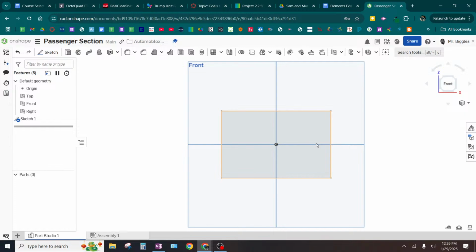And I'm going to measure the dimensions of this. When you open up the calipers, you've got two pairs of teeth. These teeth down here, the bigger ones, go around things like that. They go around stuff. The ones up top, if you notice the edges that are straight are on the outsides, are for fitting inside things. So the big ones go around stuff, the little ones go inside things.